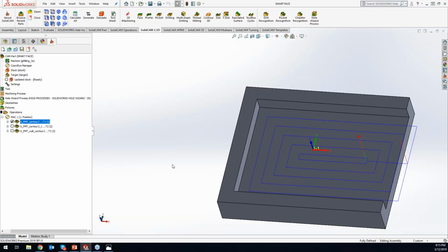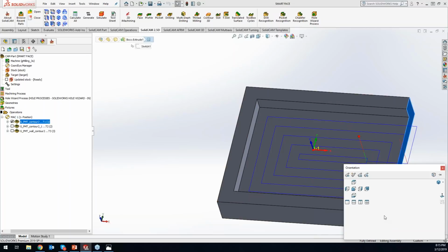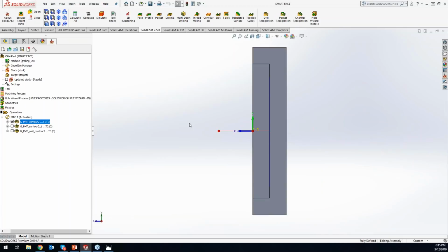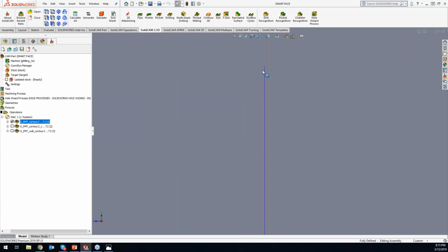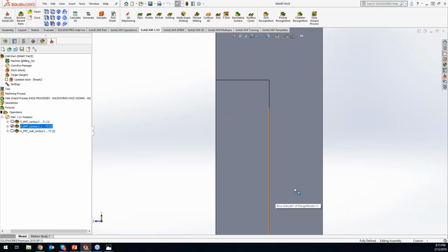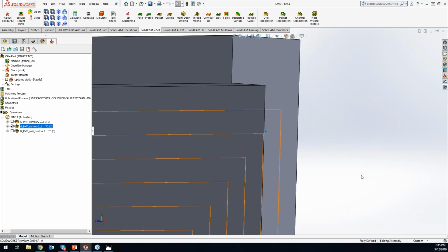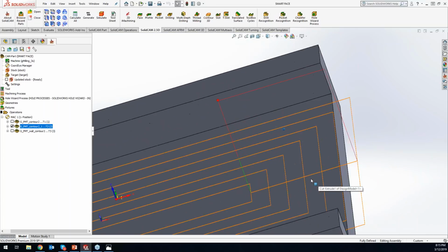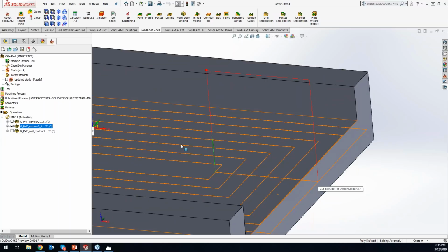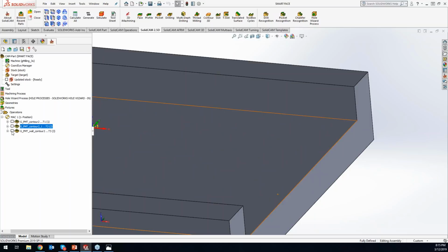Yep. So right here, we're doing a roughing. And let me just get a front face view here. And you can see that we're sitting off the floor right here. Turn this one on. And this one is now doing our finish of our floor with a smaller tool. And let's say this 3/4 inch is maybe like an insert mill, or just a corn cob cutter, or just any kind of roughing tool. Coming back with a finishing here.